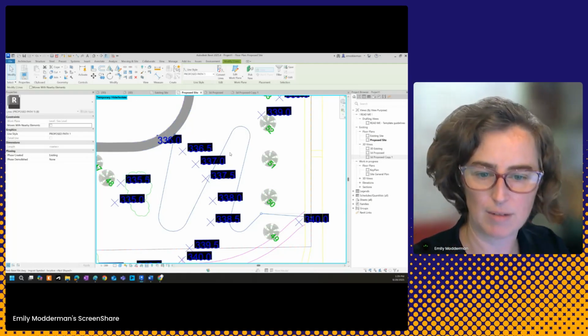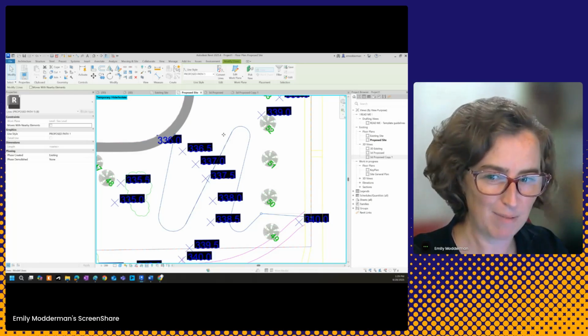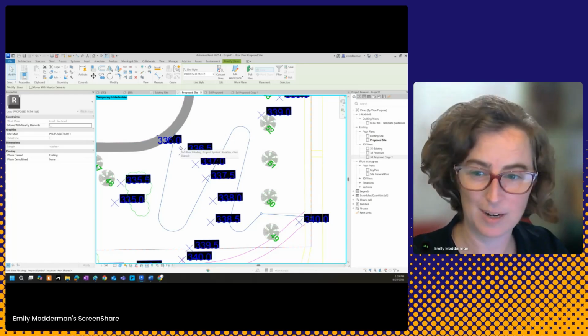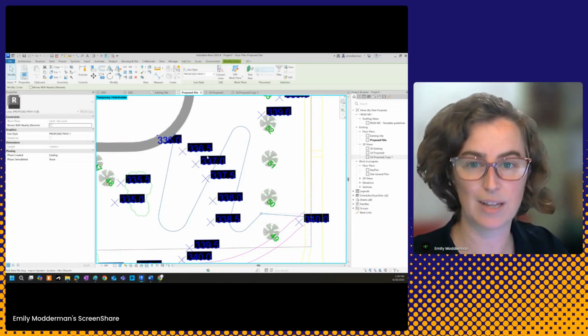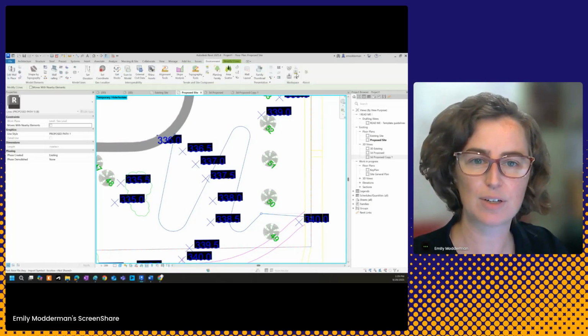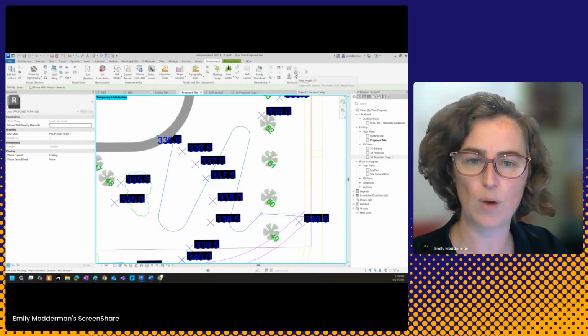And I've got a pathway here that I've pre-built. Now, one of the things that's annoying in Revit that environment can help with is I've built this pathway, but it's a lot of smaller segments. How do I actually know what the length of it is? Well, there's a terrific little tool in environment that shows you that information. It's on your environment tab on the far right.